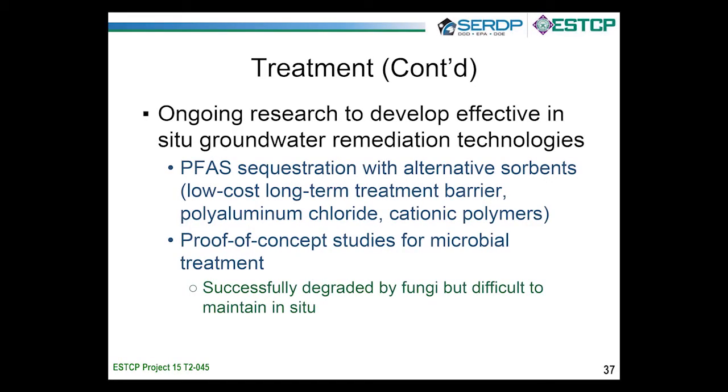So far, over 300 microorganisms have been screened for their degradative capabilities for PFAS, and none of these microbes that are effective for 1,4-dioxane, MTBE, and other emerging contaminants or chlorinated solvents had any luck breaking down PFOS and PFOA. There is some limited work out of UCLA with fungal cultures where PFOA degradation was shown using white rot fungi, but very limited success with PFOS because of the stability of the molecule.